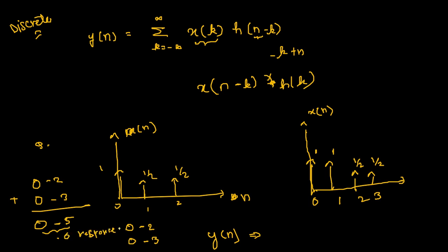Okay, so now let's start performing the convolution. Like I said, the first thing we'll do is replace x of n and h of n, and n with k, right? So let's fix our input signal. Let this be x of k. So the input signal is fixed at this particular point.